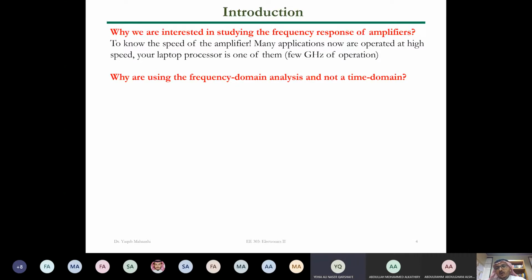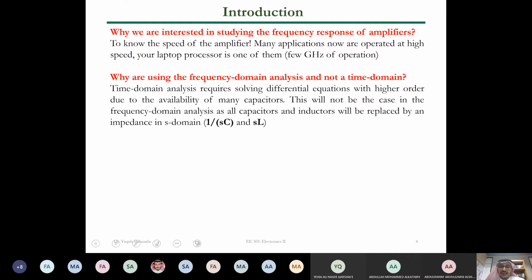Exactly. If you have more capacitors in the circuit, now you have a lot of differential equations. So it's much easier to analyze the circuit in the frequency domain, because now you are doing Laplace, which is 1 over SC for the capacitors, and you deal with it as Z, like an impedance. So it is much easier, and it also gives you more insights into the operation of the amplifier over a wide spectrum.